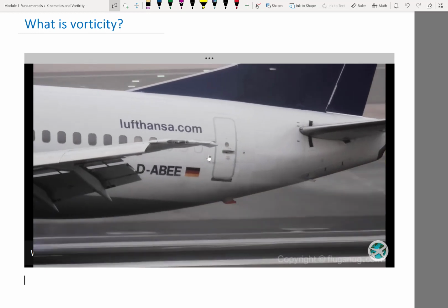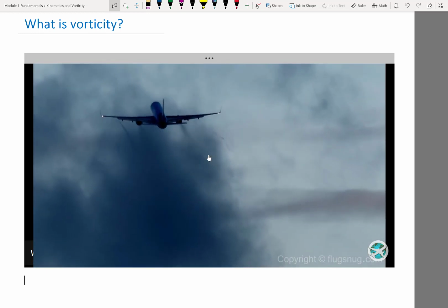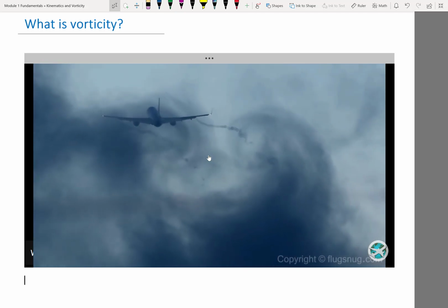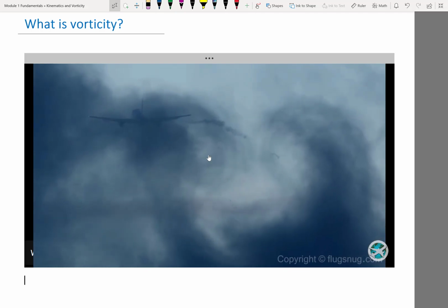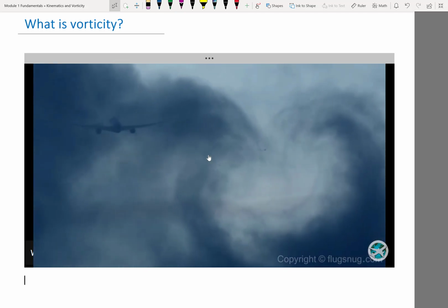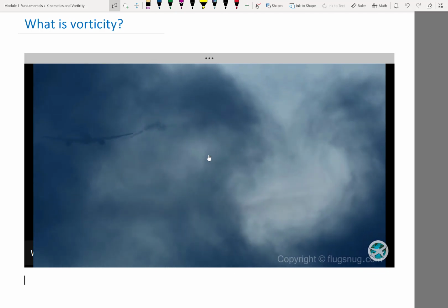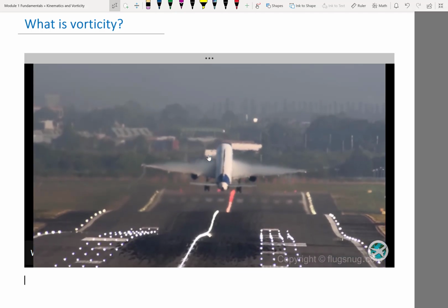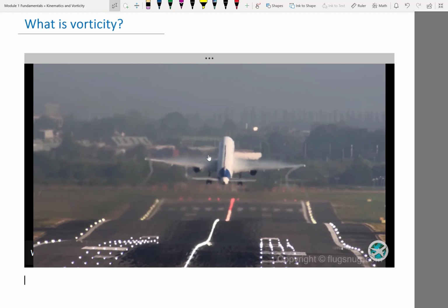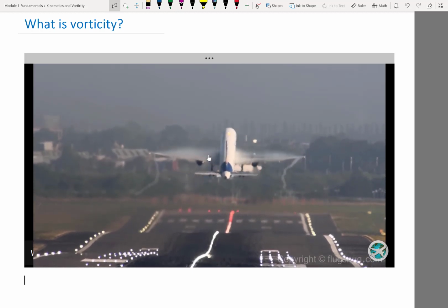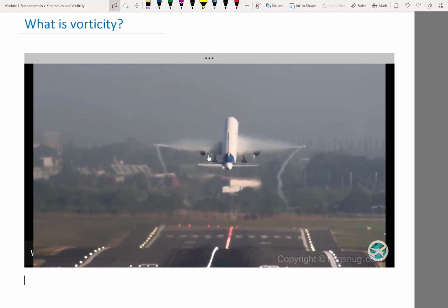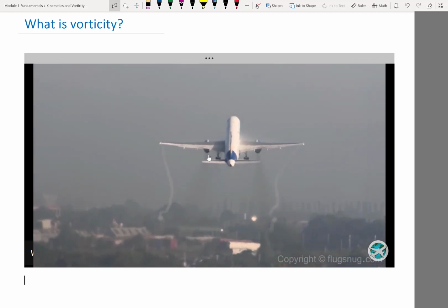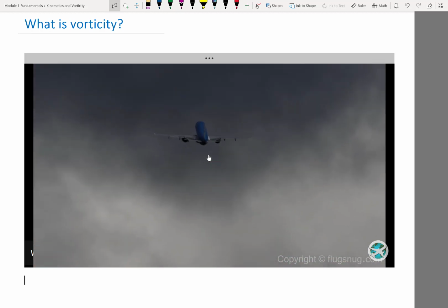Exactly. So the reason you see the moisture being visualized is because there is condensation, and there is condensation because the temperature over there is lower than the temperature in surrounding regions. Actually, both temperature and the pressure. So air is being expanded in the region where you see moisture condensation, right? So basically what you are watching is regions of low pressure, and as a result also low temperature, because as you are expanding air to low pressure, the temperature drops, right?